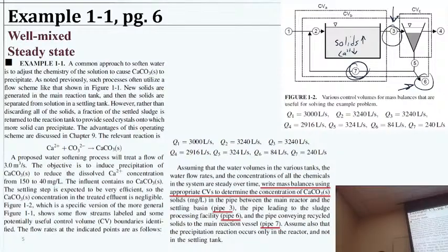Concentration of what? Yeah. So a good point in question there. With a clarifier like this, we have liquid water with dissolved stuff flowing in two directions, right? From 3, we enter the clarifier. We have liquid going out here and some liquid going out here. Anything that's dissolved is not going to be separated by gravity, right? So the concentration of anything dissolved should be the same in those two outputs.